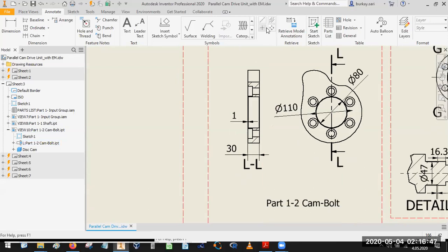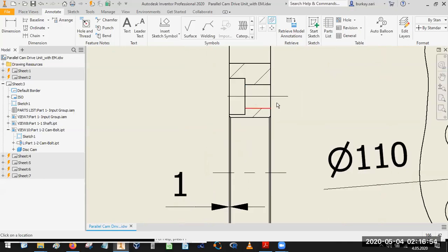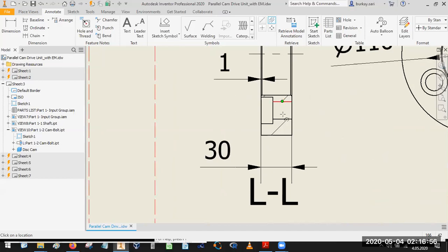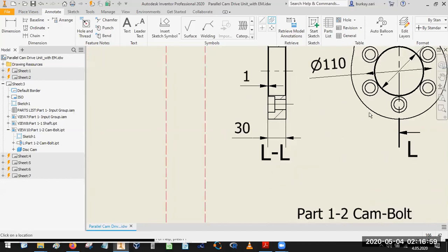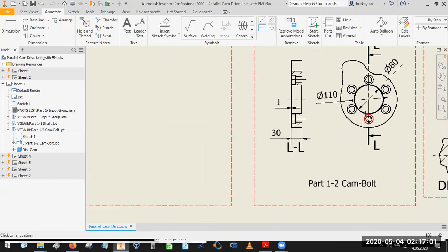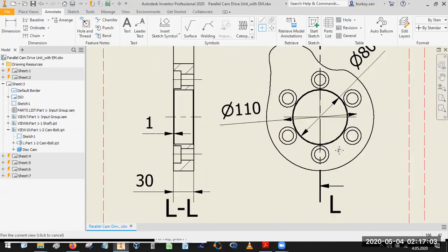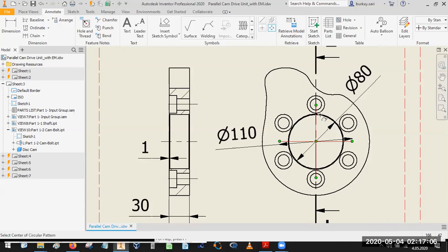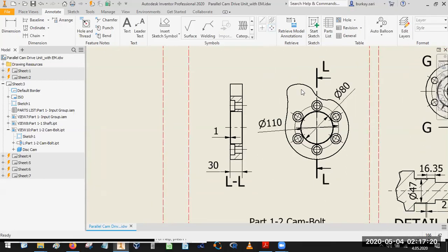I would like to add some dimension constraints, some small axes. I would like to add a big axis on this one. For the rotational axis, I will use this center point and hit the create button to get this one.